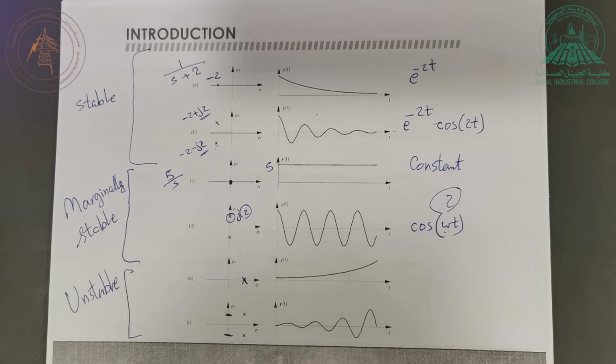An op-amp, for example, has between 20 to 30 transistors. So you can imagine you have a huge number of poles, so it is very easy for the system to become unstable.